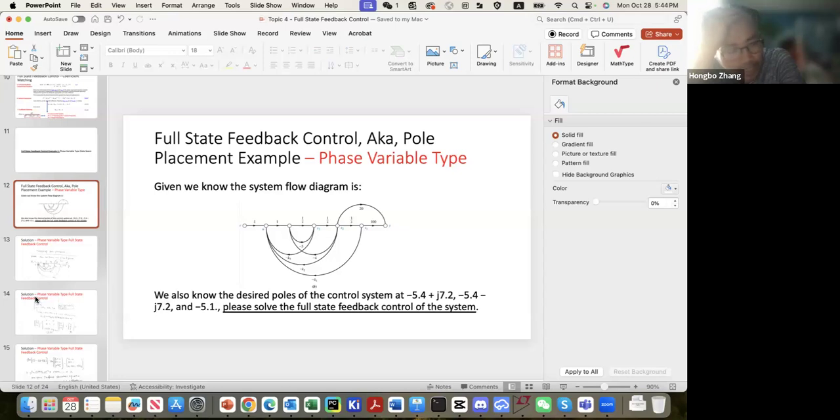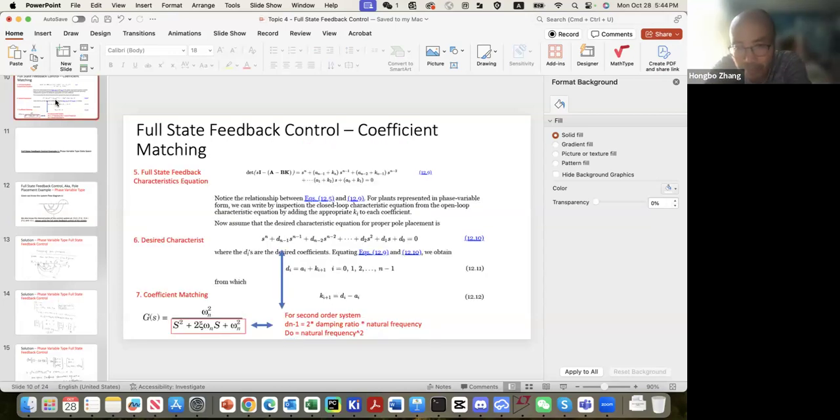The way this one is a little bit different from the optimization approach is this one is really based on we want to know the desired pole locations. And you say desired pole location is easy, right? Because for a certain settling time we can calculate the desired pole location, but this is for second order. But most systems are probably third order, fifth order, right? For drones, we have sixth order, even 12th order. Actually, you already worked on lab 3, right? You found it's pretty hard to make a 12 by 12 matrix work. So it's not that easy, by the way.